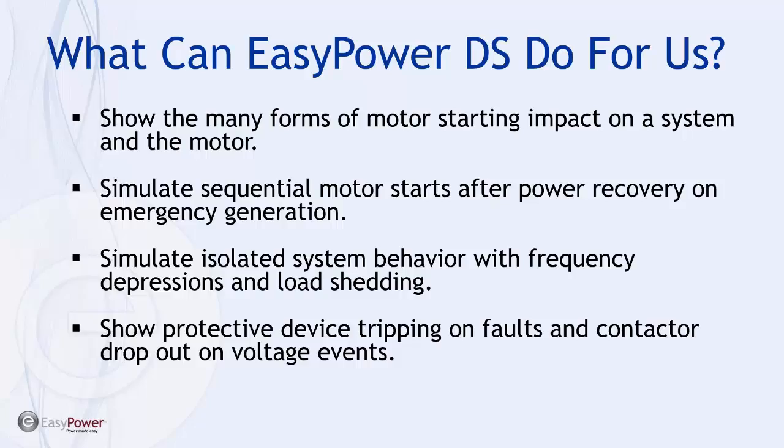For instance, take a cogeneration station, which happens to be fed by a utility and a cogenerator. What happens when the utility drops out? How long does it take the system to pick up the load, and is it fast enough to prevent outages of critical equipment? Can we recommend, say, a load shedding scheme that will keep critical system loads up and running until the cogen recovers and carries the rest of the system by itself?